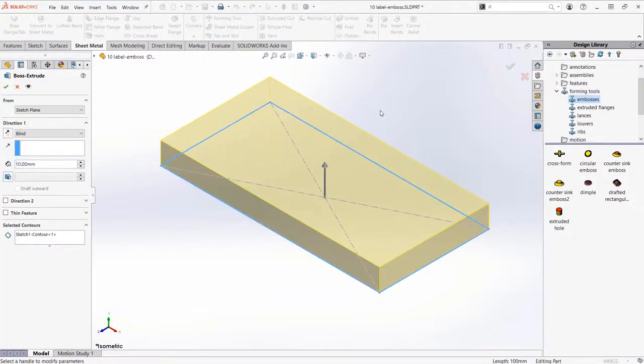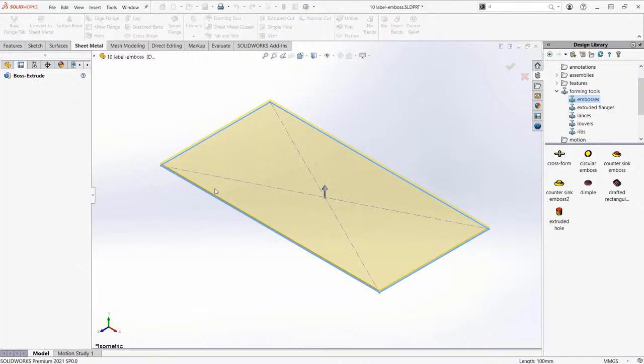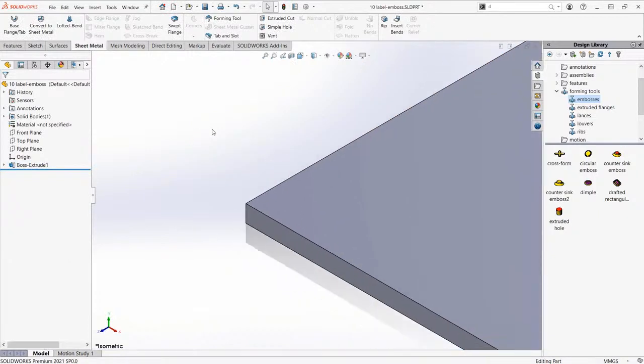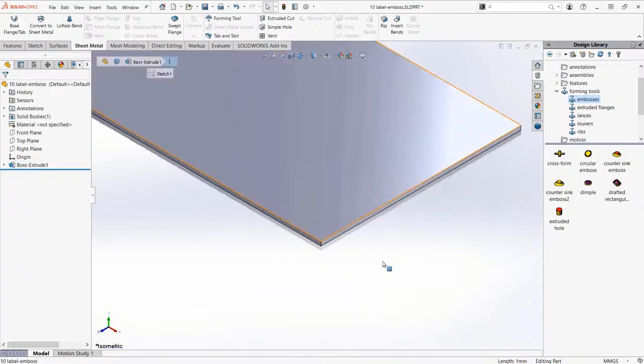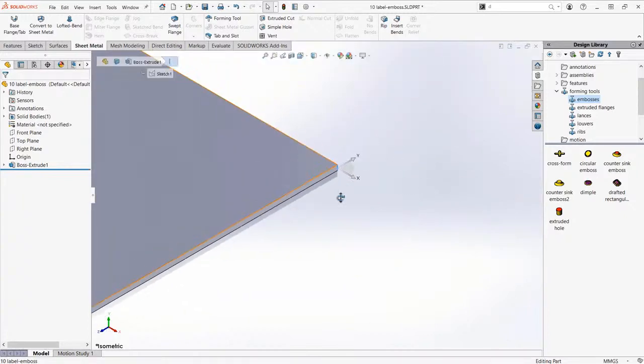So once more, our previous sheet metal has a thickness of 1 millimeter. So I prefer conforming to that. Keying in 1. And let's commit to this, selecting OK. Next, let's now add the fillets. So I'm going to select these 4 edges.